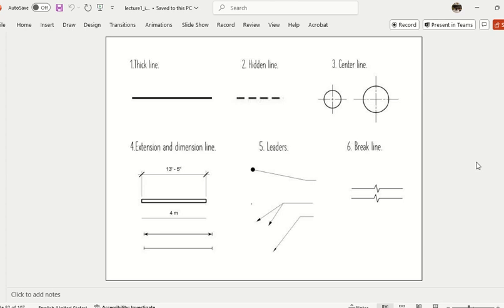So this is my room, and this is my roof. Okay, but the column goes to the top as well, right? But my plan is only up to here. My drawing is only up to here. So what will I show here? I will show a line like this. This is called a break line. Okay, so whenever I see the break line, I know this object is continuing. I don't see it in the drawing, but it is continuing. Got it? Clear?